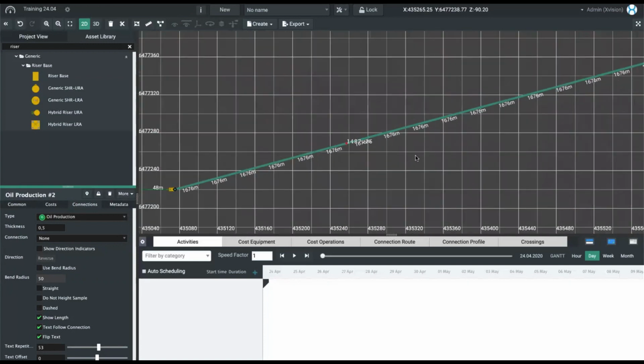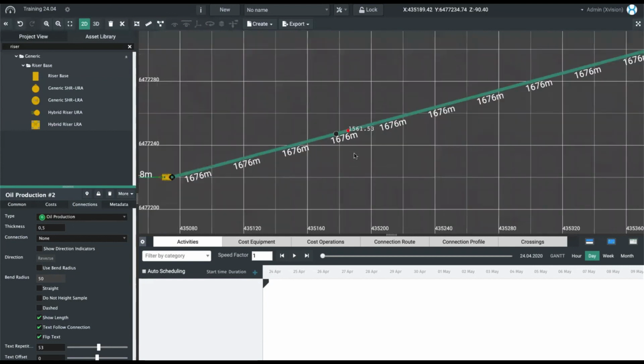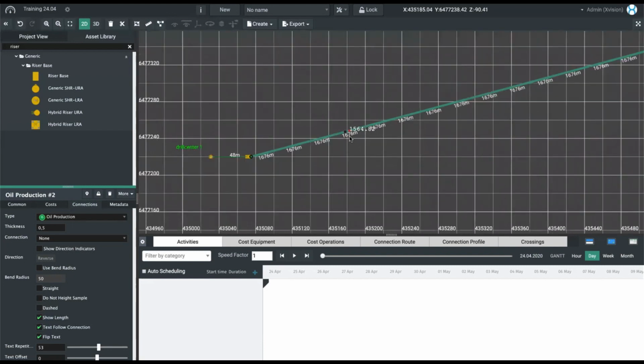This is useful. And there's two ways in Fieldap to make a pipe route. One of them is to just click anywhere on the connection. You generate what we call an intermediate point. And if you click that point and drag it, you have this kind of spline functionality, which you're probably familiar with. So if I click here and drag that one up, I can then manipulate the route. And you can see that the length of the connection automatically recomputes when you do this.